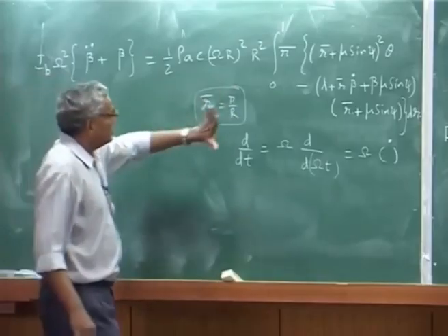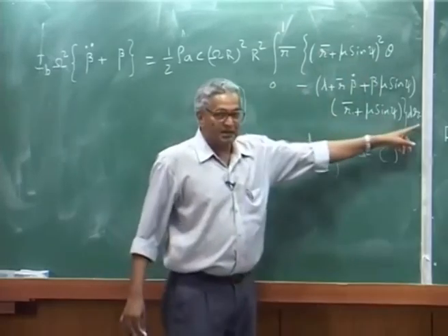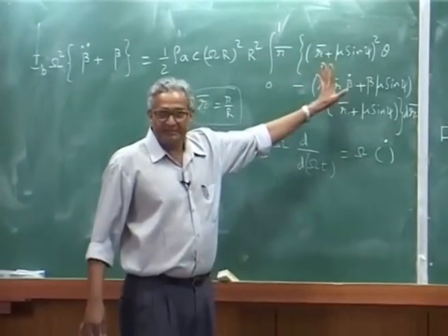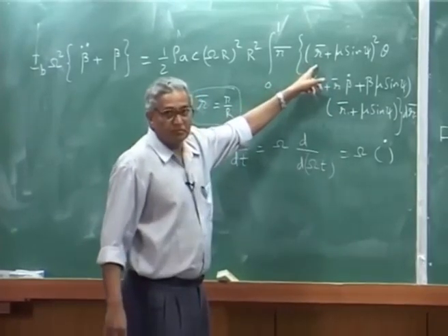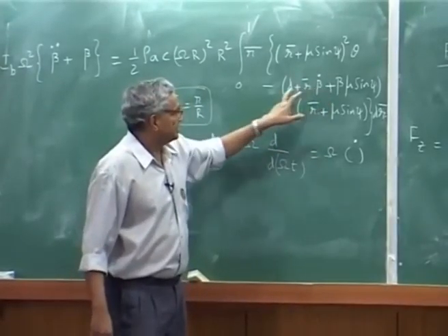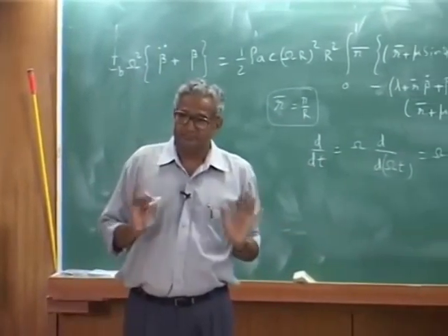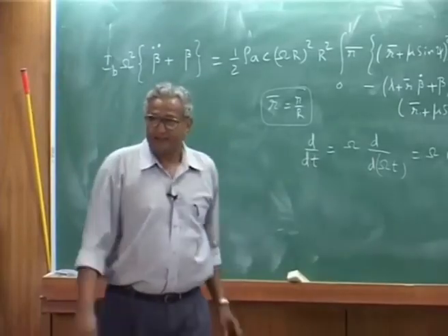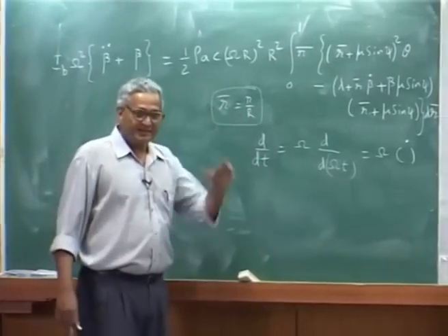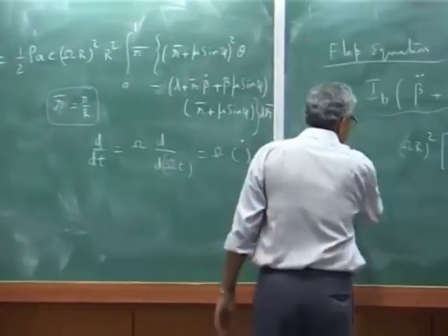Now you find within this is an integral over dr bar. So I can actually multiply everything, because mu sin psi, beta dot, lambda, assuming lambda is constant over the span, then I can integrate the entire thing for r bar separately. Write the moment equation in a relatively simpler form.